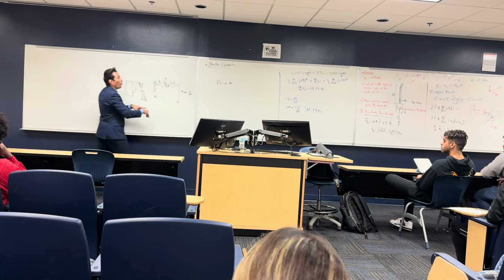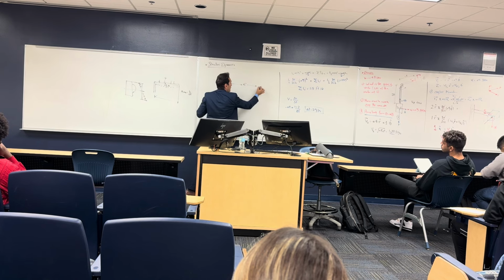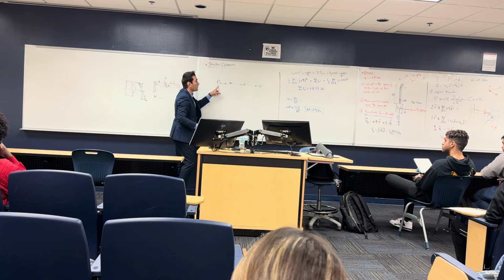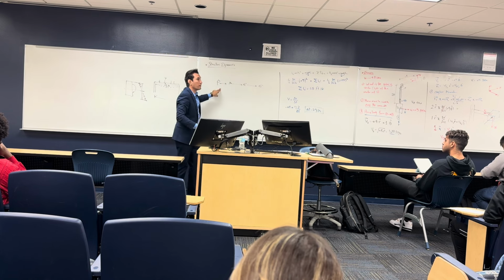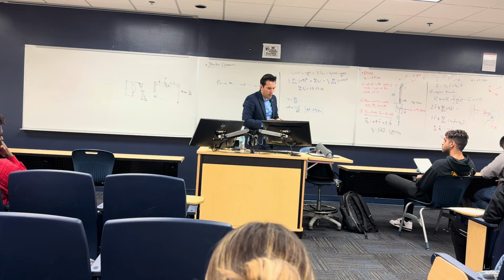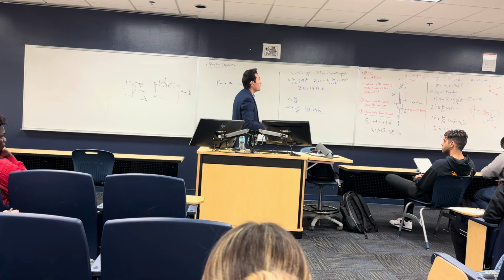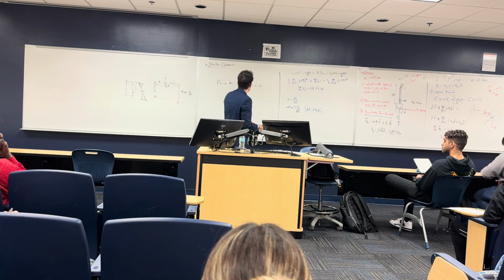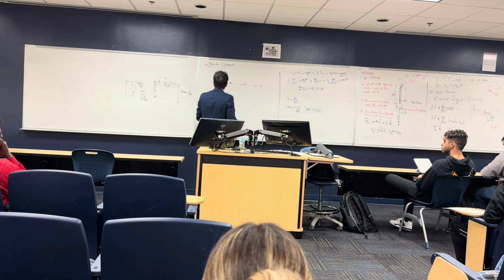So the delta makes strains, and the strains create the stresses. This is loads, deflections, strain, and stresses. That's the cycle of structural analysis. Our job is to get the displacement that happens in the structure. We need to find this delta: is it beyond the maximum or below the maximum?